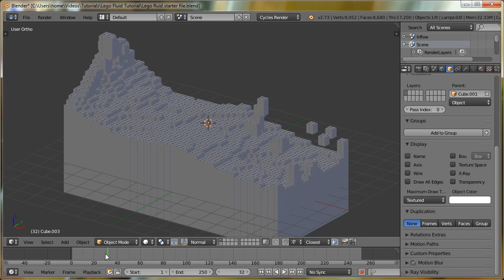If we had this and we said, right, well we could use particles to replace every vertex of the mesh, and you know there are some advantages of using particles because we could have slightly randomized rotations and things like that. The only problem with particles is that it expects to know a specific number of particles you want, but unfortunately with this fluid we simply don't know how many particles we would need, and so you could say, oh well I'll just put the particles up to a really high number, but if you did that and it needed less, you'd start to get particles overlapping again.